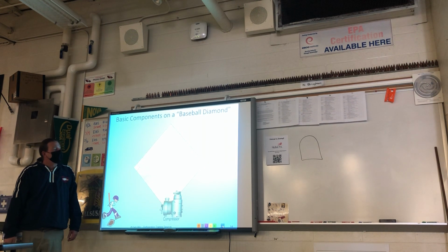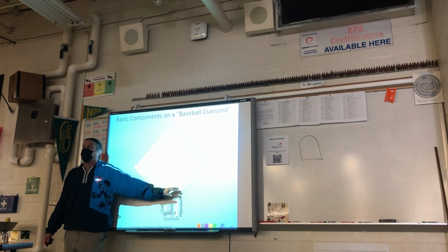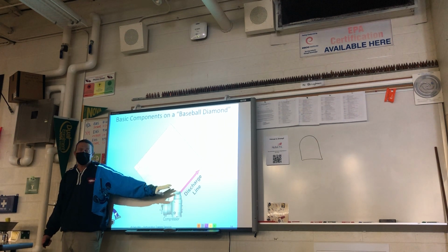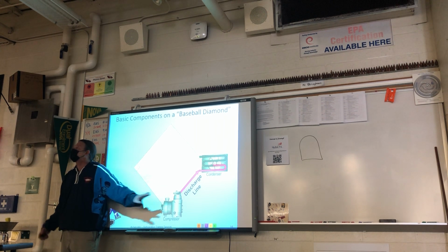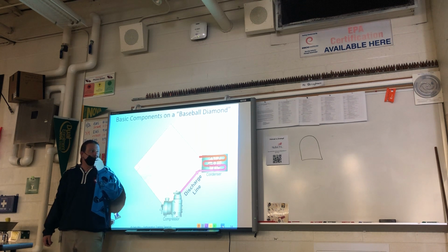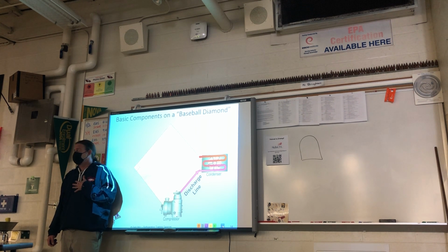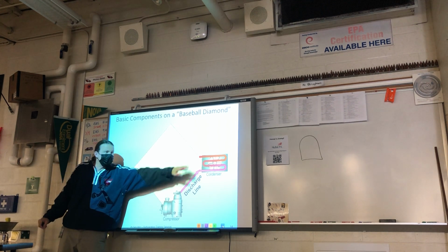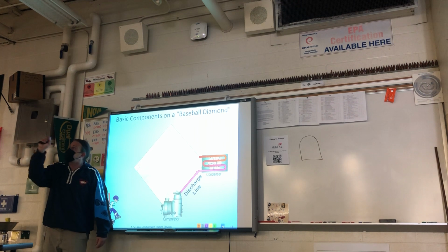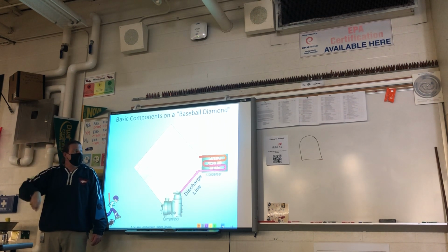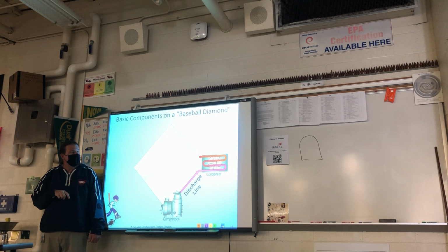So listen, what's the line coming out of the compressor then? What's my first baseline going to be? Discharge. That's right. So you go ahead, you write that discharge line, draw it with a light red, into what's first base? The condenser. So you're going to draw a squiggly, and you don't have to do the box with the fan, but do the squiggly line, right? Coming up like a coil, and then bring that up into what's the next line after the condenser?